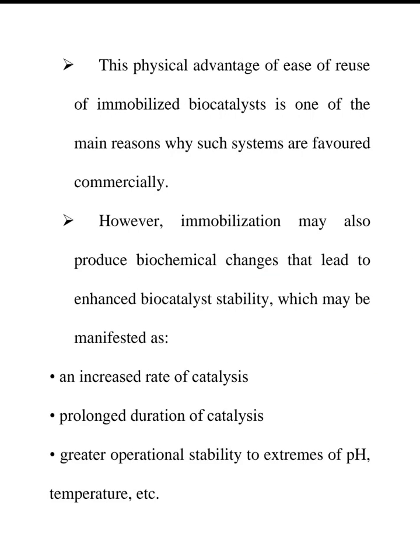This physical advantage of ease of reuse of immobilized biocatalyst is one of the main reasons why such systems are favored commercially. However, immobilization may also produce biochemical changes that lead to enhanced biocatalyst stability, which may be manifested as an increased rate of catalysis, prolonged duration of catalysis, and greater operational stability at extremes of pH and temperature.